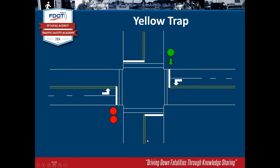And so as you're making your signal phasing choices, you want to make sure you're avoiding that trap, because you've suckered this left turner into the middle of the intersection to get hit in an angle type crash. And it really is a left turn crash, but it's an angle type crash, and severe consequences are likely.